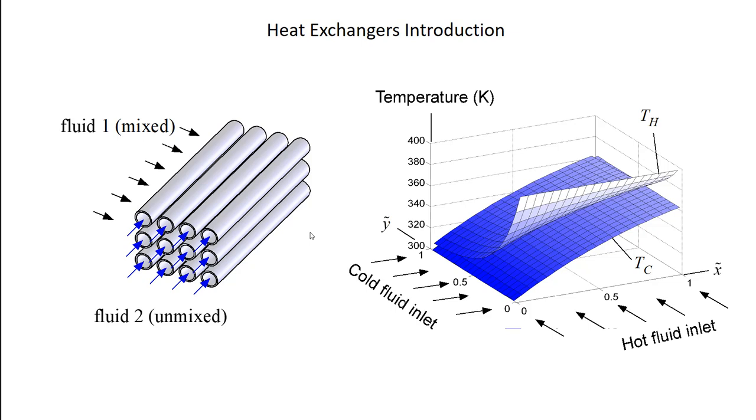The idea of a cross-flow heat exchanger, I think, is pretty easy to understand. It's a little more subtle to understand what it means when you're looking at mixed versus unmixed, or mixed-unmixed, those kinds of things. And in the end, your geometry dictates which type of situation you have, or at least which type of situation you're approaching. In reality, you won't get a pure mixed or a pure unmixed behavior, right? But you'll approach one or the other, and that's the solution you should use.